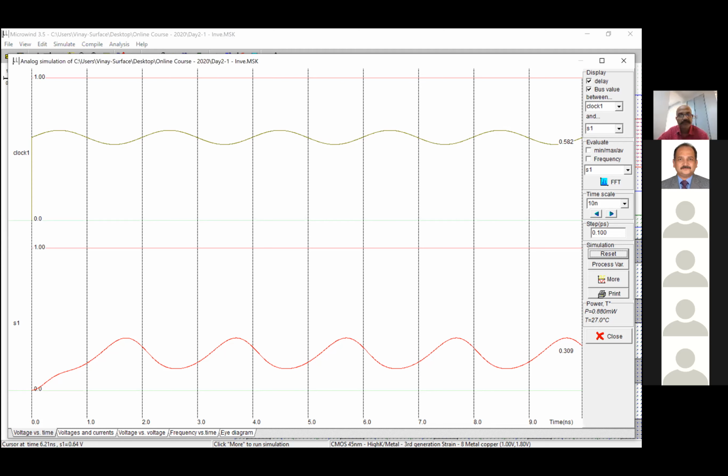Okay. Because this is an inverter, that's why there's a phase shift. That's why it gives an inverting output. And this is just a basic amplifier. Technically, you can't make use of an inverter as an amplifier in any of your projects, because the gain and the current will keep on changing with the slightest change in the load, which is not desired in a professional amplifier.